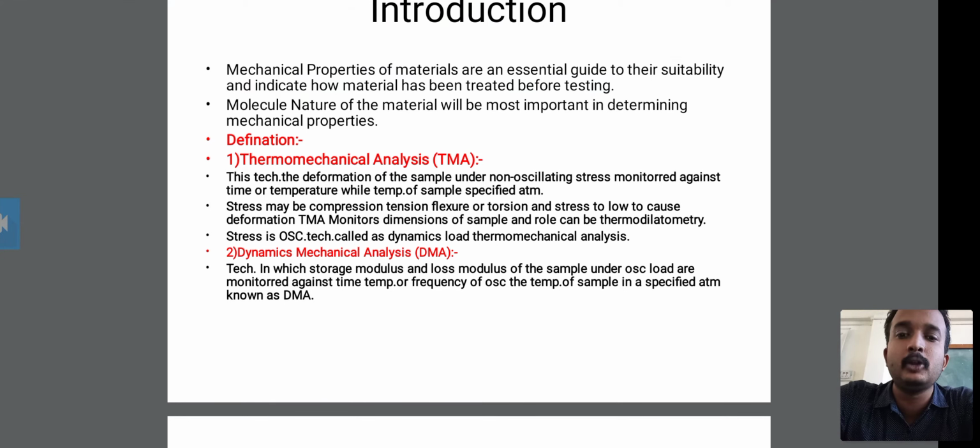Then the stress may be compression, tension, flexure or torsion, and the stress is low enough to cause only deformation. TMA monitors the dimension of the sample, and the role can be thermodilatometry.